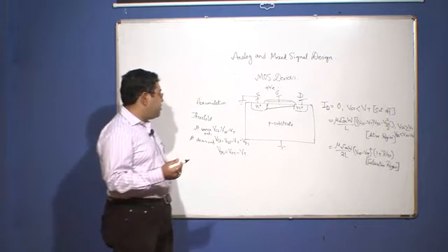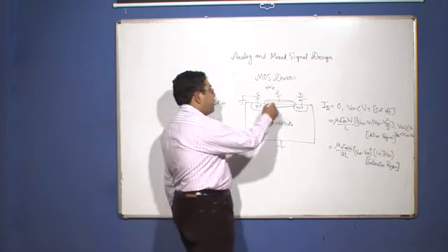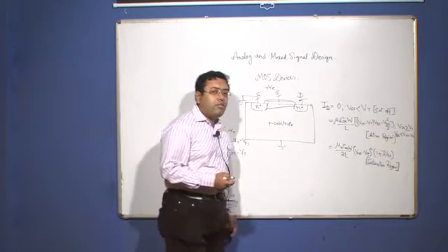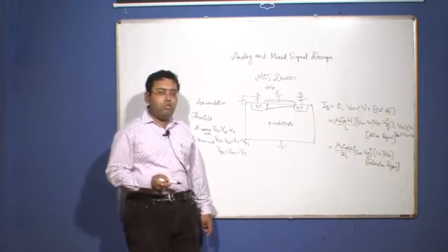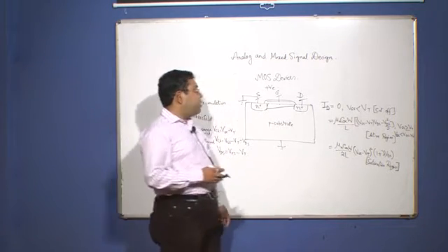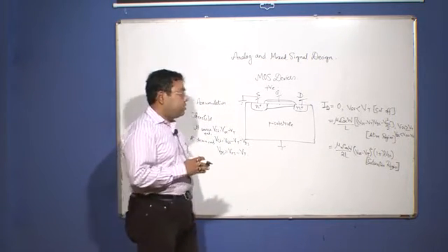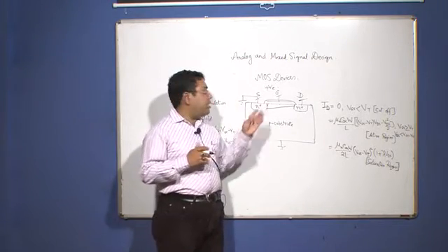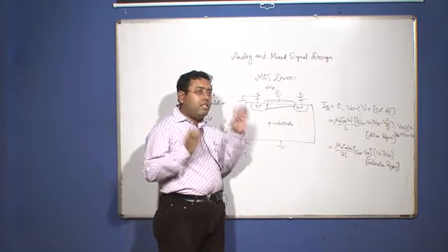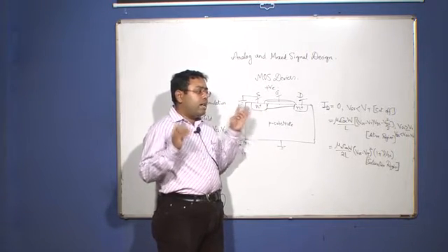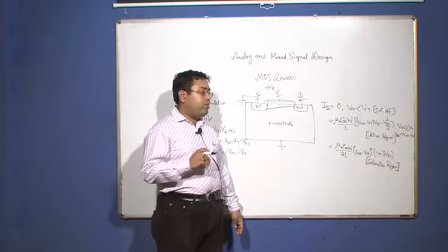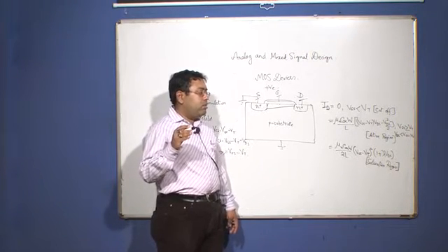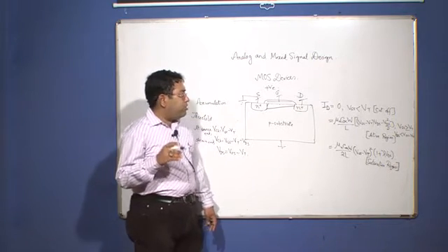If we further increase the drain source voltage, this pinch off point gradually shifts towards the source. The point at which the drain source voltage becomes equal to the gate source voltage less the threshold voltage is the pinch off point. But there is a very important point over here: beyond the pinch off point and up to the drain, there is still conduction, because current doesn't stop beyond the saturation point. It still continues almost constant except for a small slope.